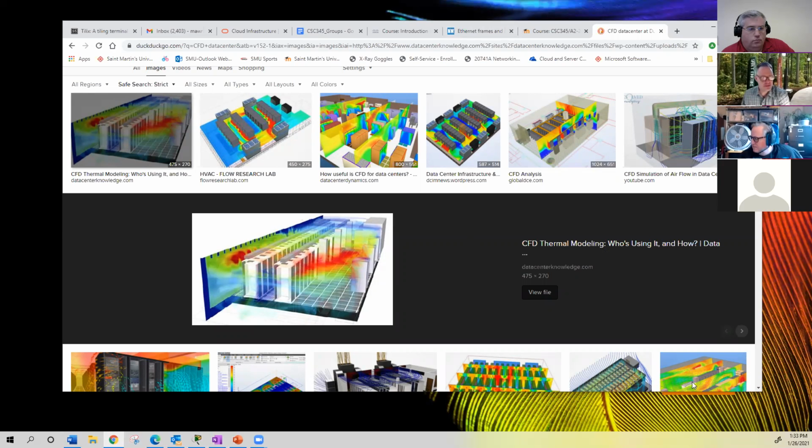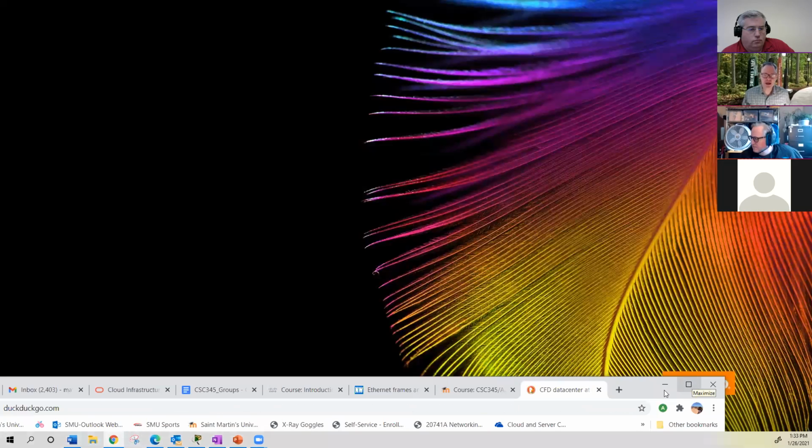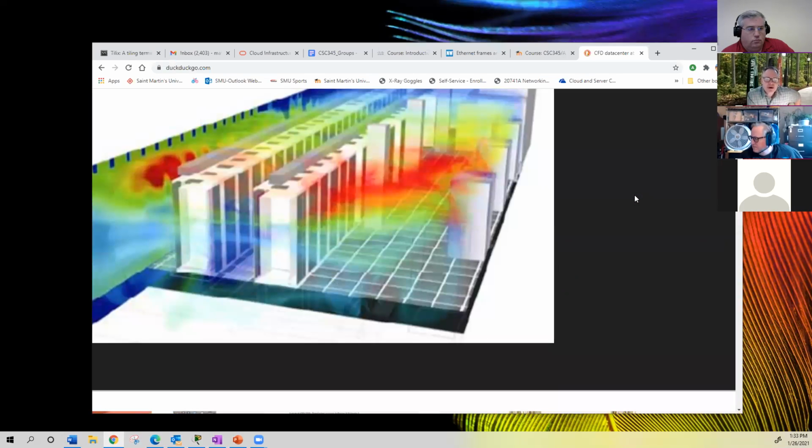This picture, okay. Bring it back up, okay. So airflow coming up here, and then it's being heated, coming up through a cold aisle in the middle of these two rows over on the left. That's your cold aisle. You can see bluer air coming up, and then it goes into the fronts of those two rows that are facing each other. And then out the back of those racks is the exhaust, the warm air.